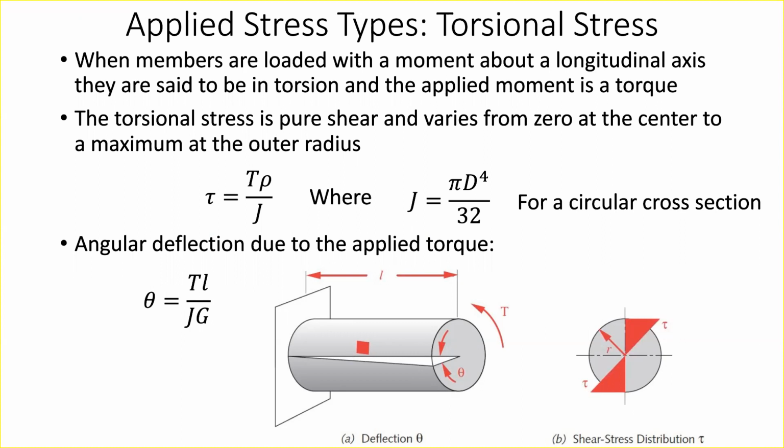And you can actually relate the shear yield point to the normal yield point. These are different per part, but they're related based on the elastic modulus. So there's a conversion from normal strengths to shear strengths, which is a little more difficult to find if you're just looking up a data sheet. But if you ever need help on that, just come and ask me and we can figure it out.